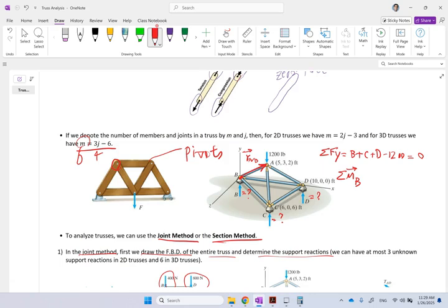And then the C force, this vector here, R of C slash B, should be crossed with the C, and then this vector here, which is R of D slash B, should be crossed with the D force, and sum of that is equal to 0.